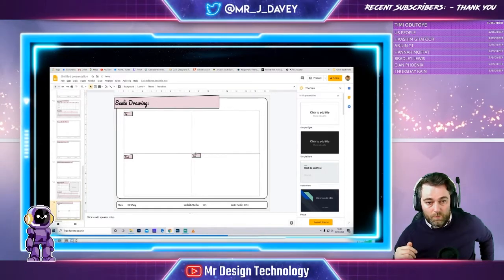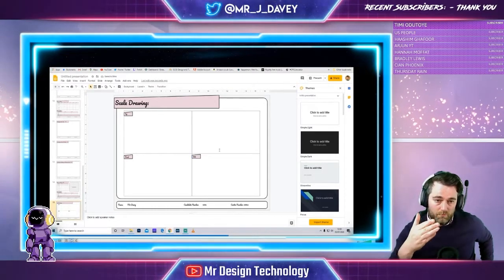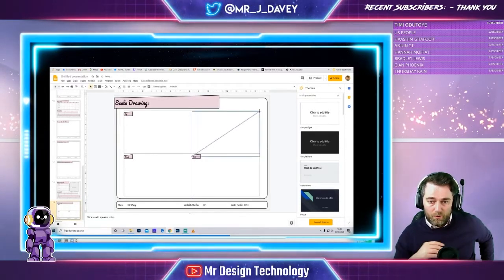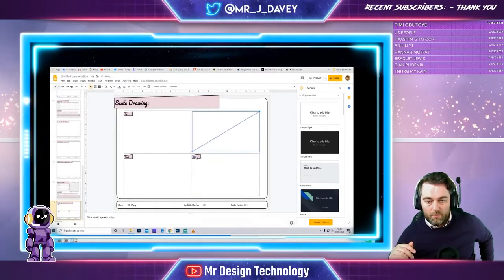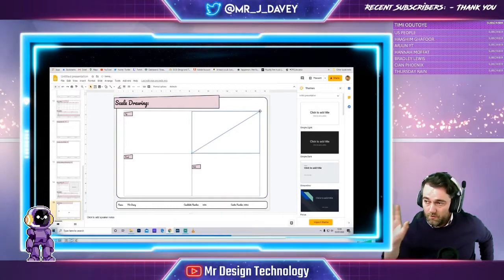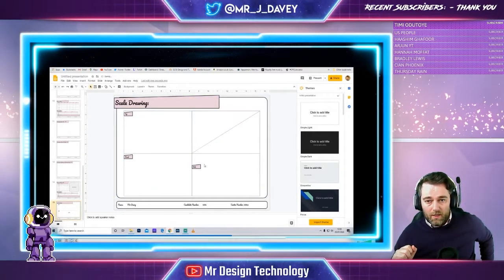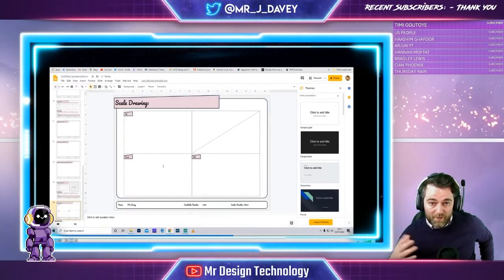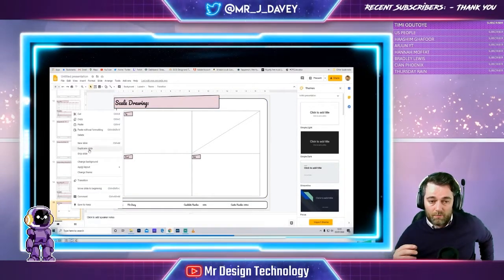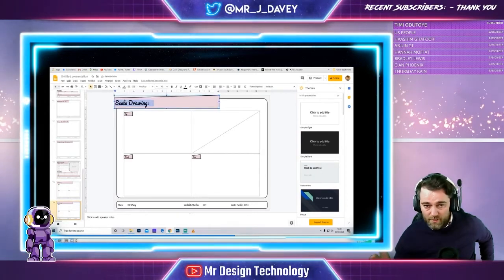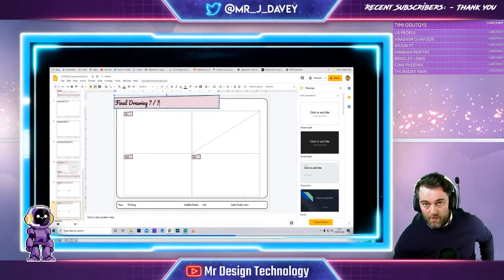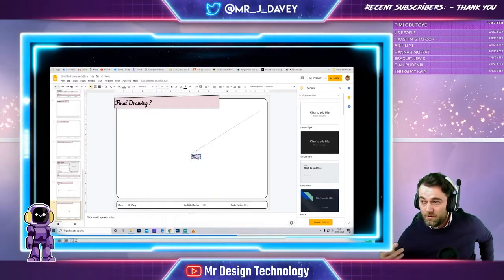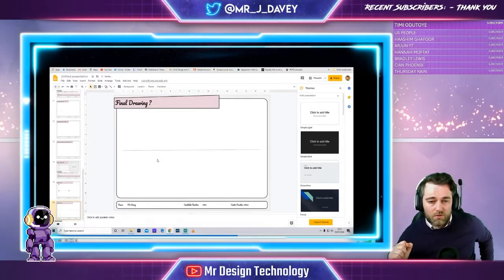So I do top view at the top, of course, front view, bottom left, and then side view to the side of it. And then just to make sure I don't get confused, I put a diagonal line so I don't put anything in that space there, so that space is out of the way. And on this drawing, I would add in all the measurements so I know how big it's going to be, and it'd be very detailed, this drawing. It'd probably take about a week to create. Lesson time, of course, so we're talking about 3 hours ish to make that.